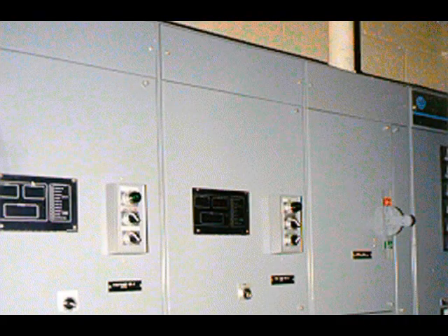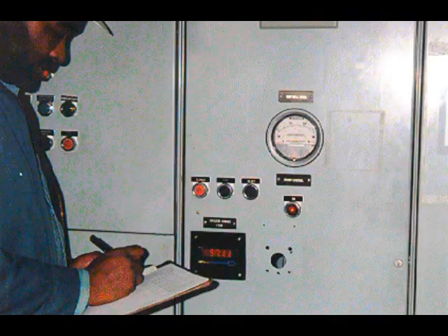Motors are usually protected at the power source where the starters for all plant equipment are located. There are other motor responses or trips that could automatically shut down the motor. These include voltage and amperage changes, high motor temperatures, excessive moisture for submersible pumps, and excessive vibration. On large motors, the motor should not be restarted until the rotor has come to a complete stop. Therefore, there should be a locking system or manual reset to prevent startup of a motor immediately after a trip.